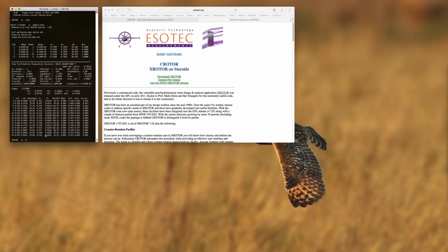And then it will give you your propeller geometry as a function of stations starting at the hub all the way out to the tip. So your local radius, your non-dimensionalized chord length, your beta, which is going to be your twist angle of the propeller, and then your aerodynamic characteristics, things such as CL and CD.